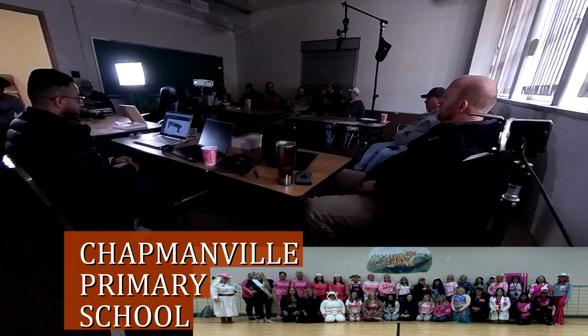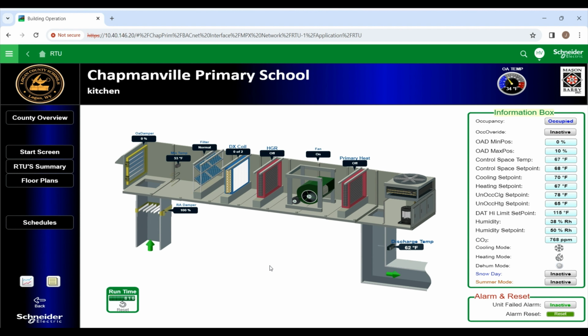But like your Daikin units at Logan Middle, there's a MicroTech inside those, and you can only write to so many points. So, for example, this equipment, the kitchen equipment, on every one of those you have the X coil. It's one compressor, two stages, a hot gas reheat, and a primary gas heat. Okay. You have basically, I think it's a multi-speed fan because it has multi-taps.